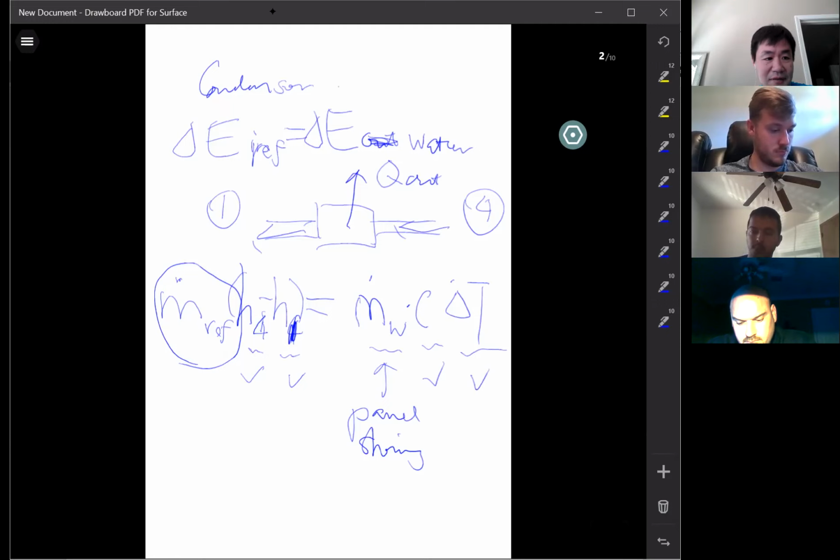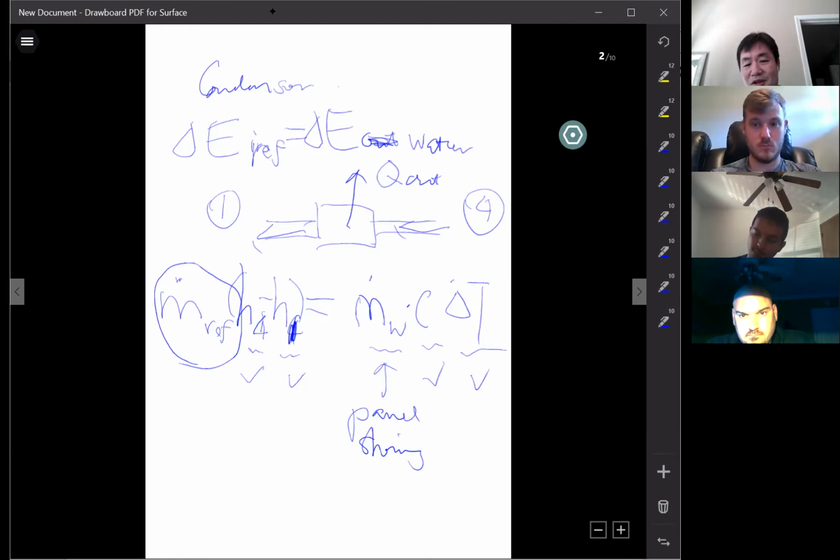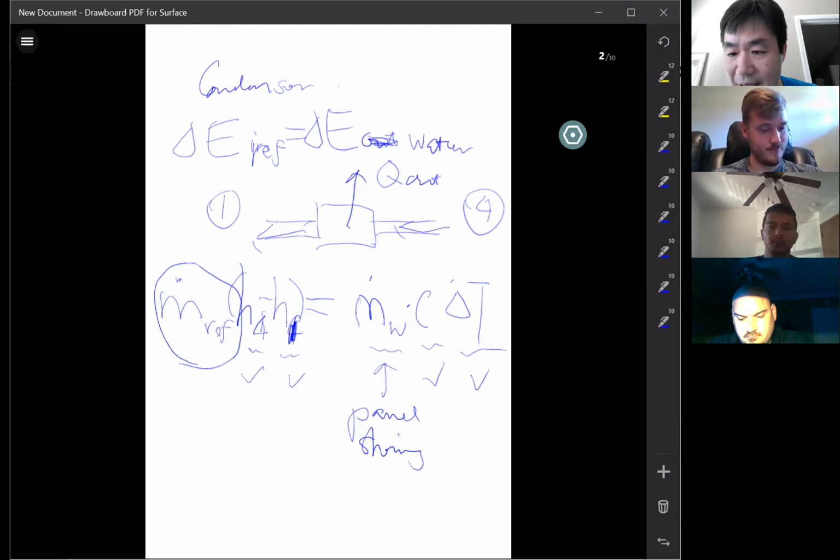One thing I want to emphasize is to be careful when it's a balance. This is an energy balance, an instantaneous balance. So if temperature changes a little bit, then you have to measure everything at exactly the same time. Then at any given moment, the equation holds. If you measure this value 5 minutes before the other value, then they're not equal anymore. It fluctuates all the time. In the video you will see we quickly do the measurement at the same time. But in reality, when you actually do the lab, I usually put at least 4 students in this lab, 2 groups together. So you can go 1, 2, 3, boom, measure all the data at the same time.